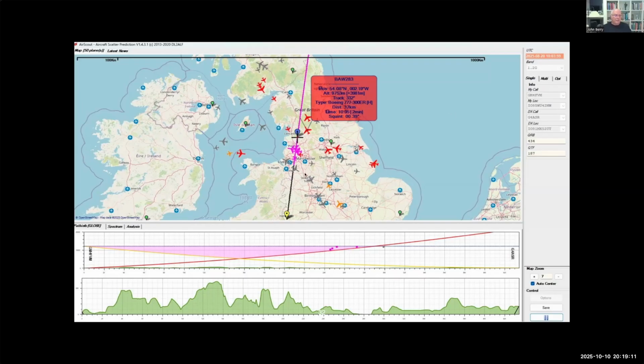The pink aircraft, here's a path between Jim Edgar, GM4FVM, and a station down near Hereford, G4ASR. And you can see the pink aircraft here. The pink aircraft are the ones inside the pink zone, and they are useful. They might give you the reflections. Now, the good thing is they're mid-path, so they'll give you an awful lot more than 15 seconds because obviously your energy from your antenna spreads.